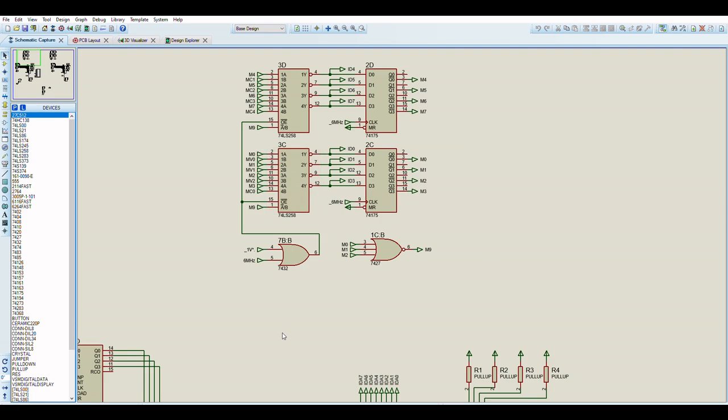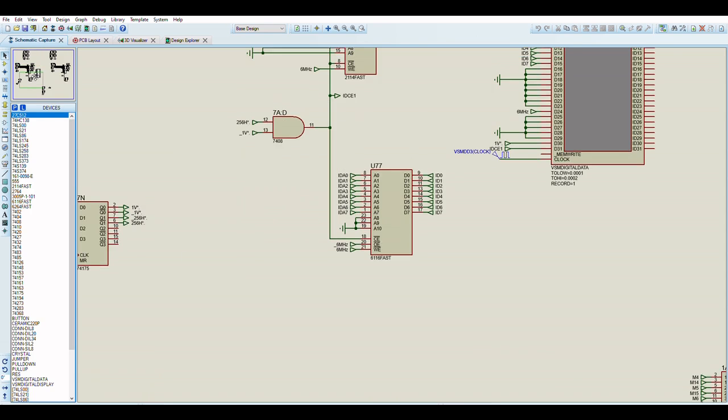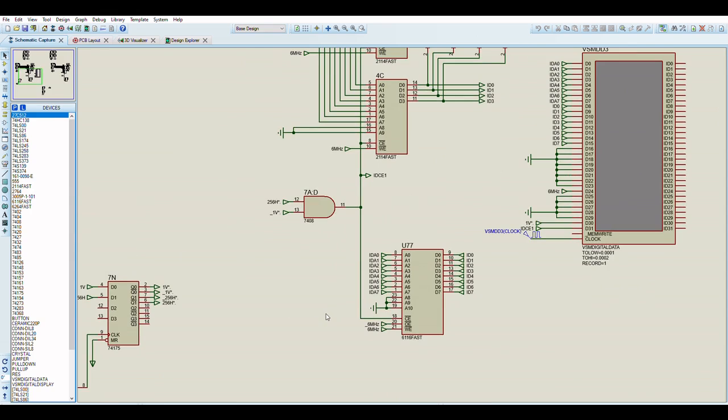on the scan line. And then at the end of the scan line, it will start outputting the visible pixels. And when it's outputting the visible pixels, it will cycle around again and start clearing the RAMs for the next odd or even scan line, depending on which side of the logic you're looking at. And then, as we saw, depending on if it's an odd or even scan line, it will demultiplex and only output the one pixel to the pixel header. This logic is really efficient.